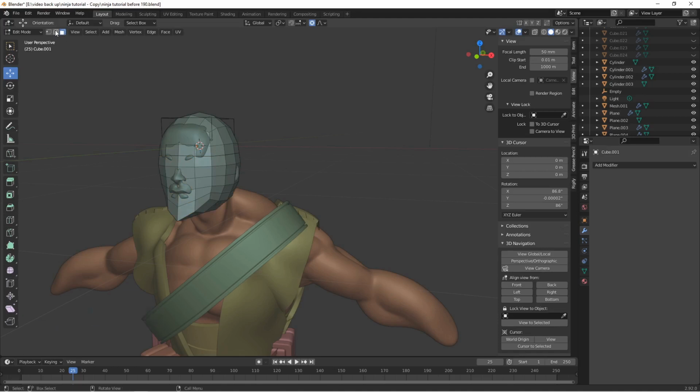I would need to go to edge select. So I'm letting go of Alt, selecting the edge, going here. I'm going to press G. Excellent. So what I'm doing is I press G. Now I'm going to press Z. See that preview line that locks me into moving up and down? So now I'm moving this down slightly.